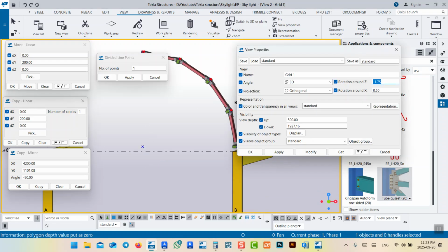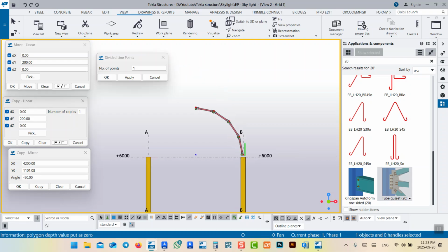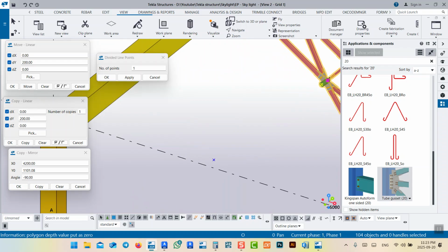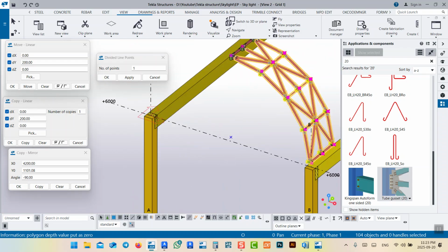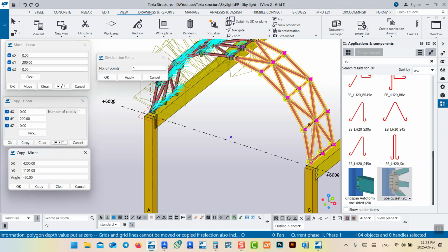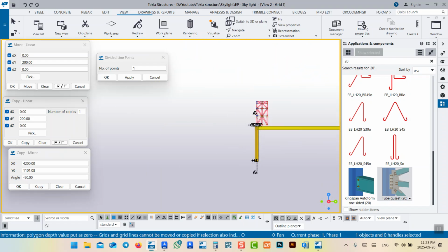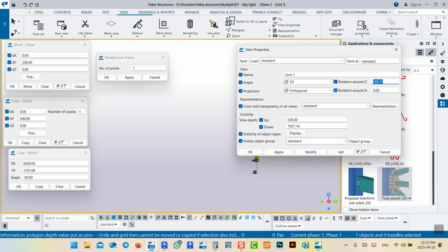First of all, what we said is that we want 0 on 0 modify, and I want to copy these parts by making a mirror. We didn't change the workplane, so it's the same. I'll say copy just like this, right click, redraw view, and this time double click here. I want -900 0 modify.